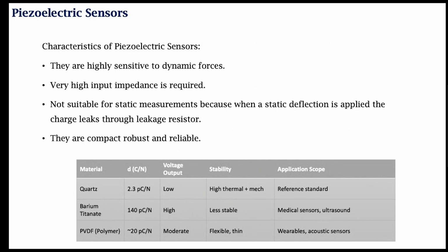Remember, they are highly sensitive to dynamic forces. That means quickly changing, highly varying, fast changes in forces can be very easily and selectively captured by using piezoelectric sensors. Usually, it requires very high input impedance.